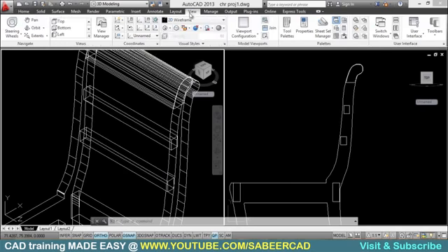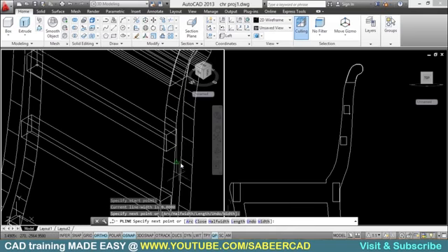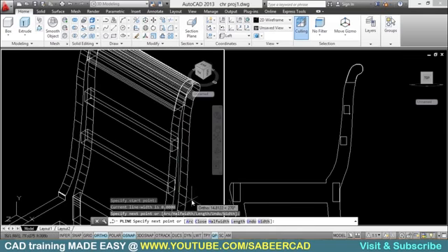So I'll go to View tab, then I'll click on Coordinate Palette. I'll select left to align the UCS. I'll go to Home tab and select Polyline, and I'll start from this point, and I'll click here. Then I'll come all the way down 10 centimeter, because you know that's a distance between those two cross members. I'll come back to this point, then I'll give a close.